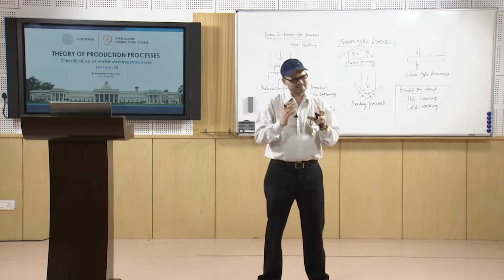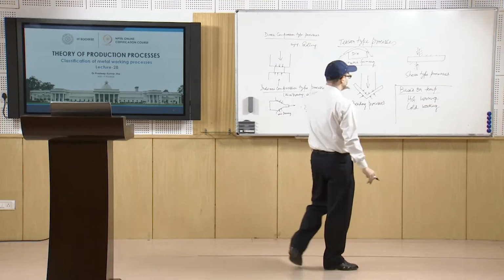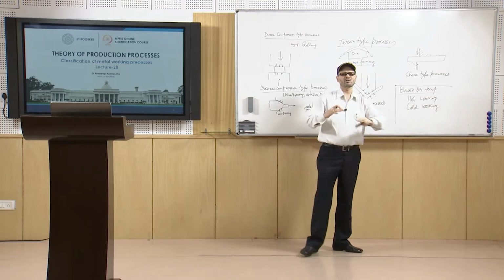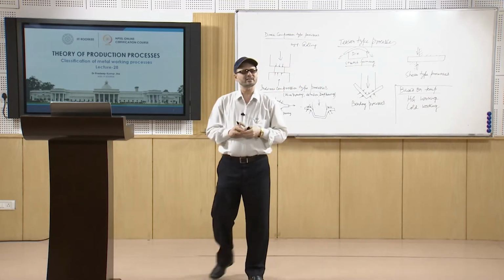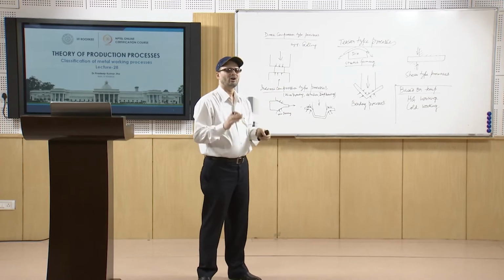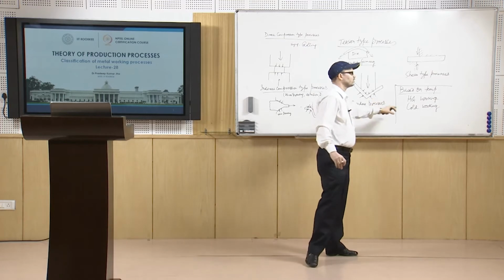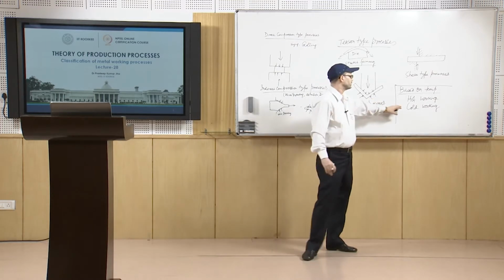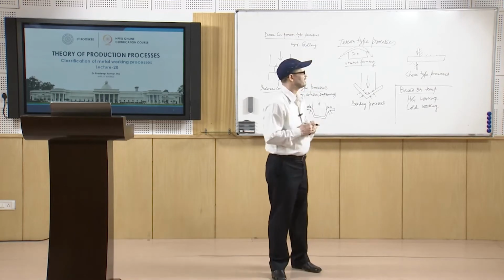So, there is basically a limit, and that is why in cases where you do not have to deform the material to a higher degree of reduction, cold working has to be done. Also, the temperature will tell whether it is to be hot worked or cold worked. For a material which is ductile, it can be hot worked, or it can be worked even at lower temperature.